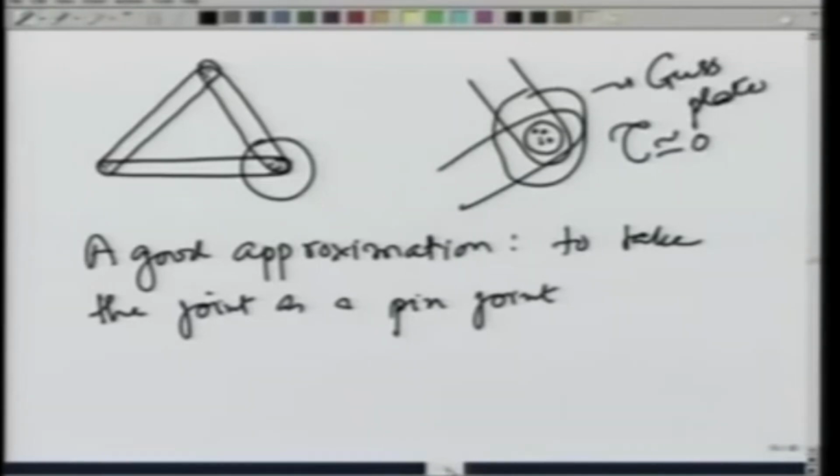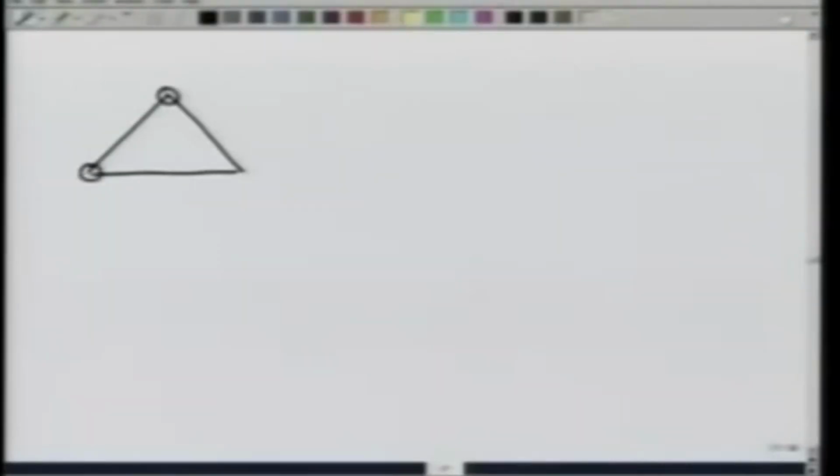So, let us see now, given a basic truss like this which I just solved for, how can I make a bigger truss? Let us see, if I want to extend this further, I put a member here and give a joint here. This joint now has 3 members that can provide equilibrium. Then this point, suppose I do not want to provide a support here, I have to provide one more member, and I could provide a fixed support here, a fixed support here. That is one possible truss.